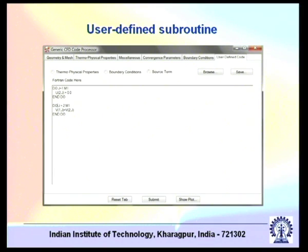Now the user defined subroutines. You consider the left boundary. At the left boundary the velocity was neither inflow nor outflow nor wall. So you have to write a user defined function: first, u equal to 0, and del v del x equal to 0, that means v1 equal to v2. Remember for V you are starting the index with 1 because it is not staggered along x; for y momentum it is staggered along y, so V is not staggered along x. That is why the indices for V are 1 and 2. These are subtle things, but I am repeating these over and again because they help you to write good user defined functions.